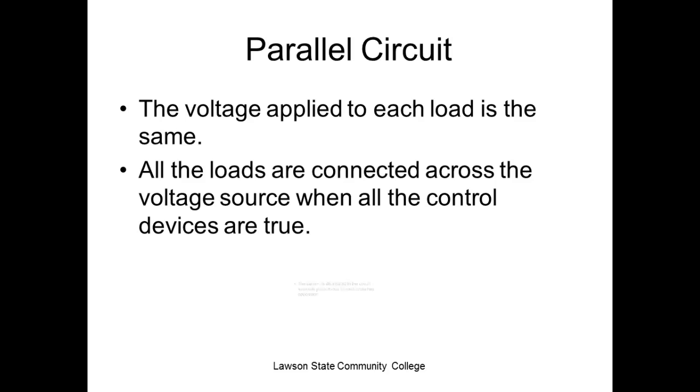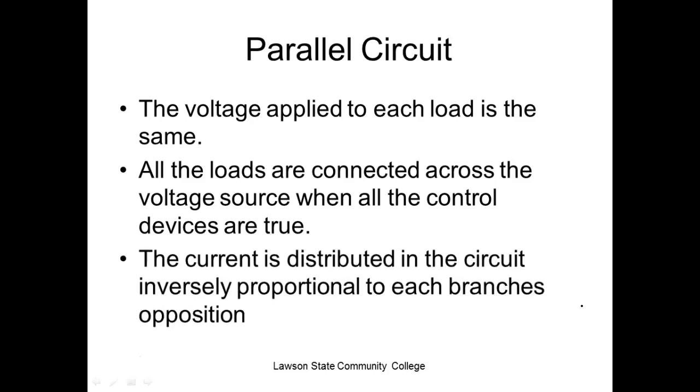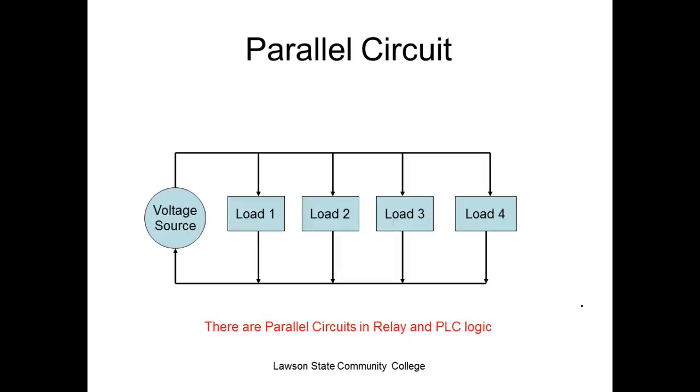So what is one of the major advantages of a parallel circuit over series? One dot is a load. Yeah, you can add and remove loads and it has no effect on the other loads. So we can turn lights off, we can turn them on, we can turn TVs on and off, we can unplug things, we can plug things in, right? So basically Alabama Power, the power company, is parallel and your house is wired in parallel. So we can add and remove loads without affecting any of the others. So this is a parallel circuit.